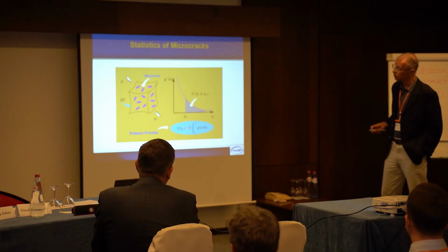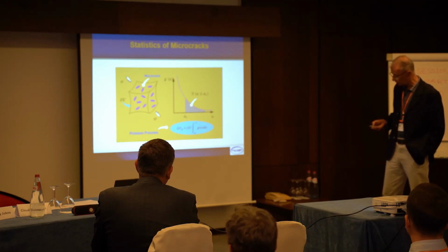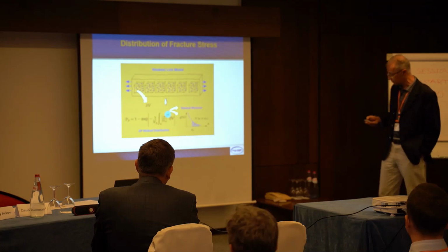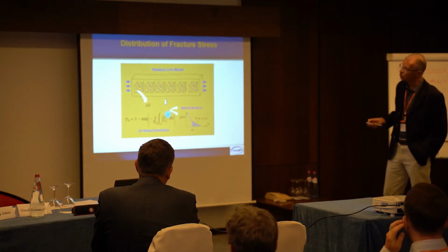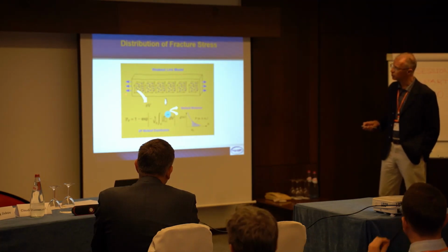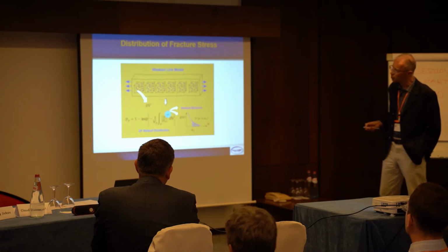By using an ad hoc microcrack distribution and weakest link assumptions, we can arrive at a Weibull distribution for the fracture stress, okay? Where the Weibull modulus is the key parameter.